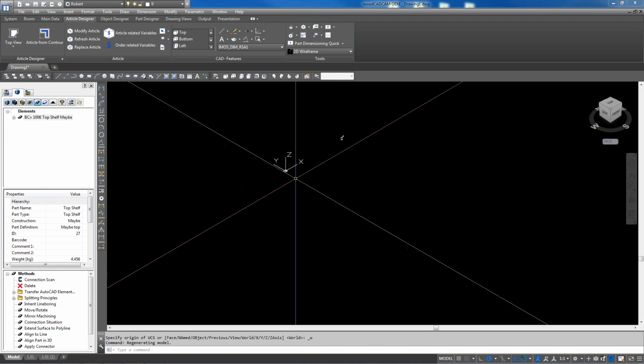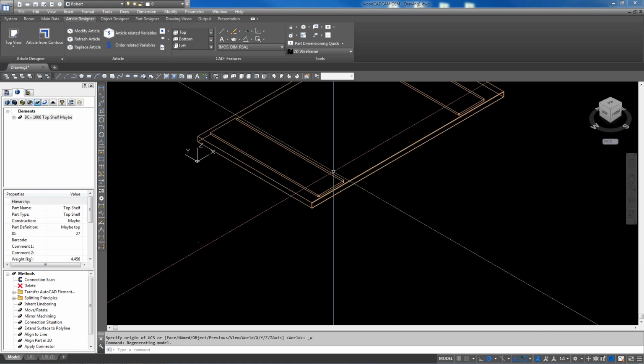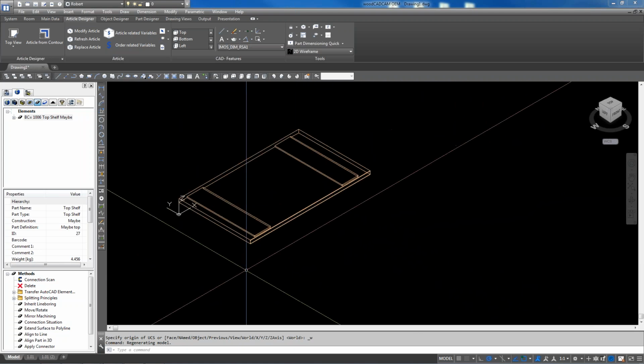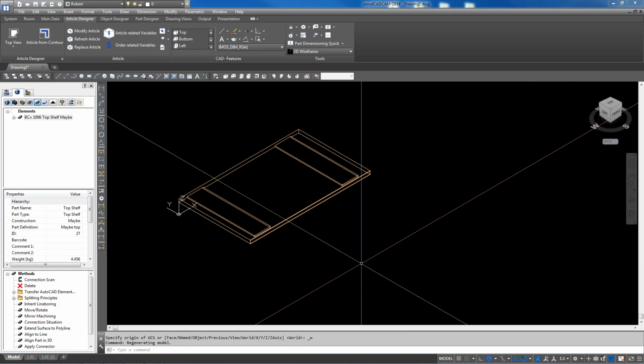Why is it so wide? What's this shelf support look like? Like steel tube or something? Not a tube, but a flat 4 inch L bracket. So it's being mounted to the wood stud behind the sheetrock and sticks out front. The size of the pocket and shelf is just random. Usually they are pretty long shelves, and they want to have them floating, so you cannot see how it's mounted.